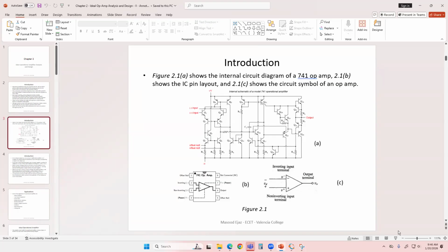The IC that you're going to use is the 741 IC. You will see a dot, basically, that represents that the pin on the left side of the dot is number 1, and it goes 1, 2, 3, 4, and on the other side 5, 6, 7, 8. Similar to the different ICs that you have used in your digital circuits. That's how the pin layout goes. On the left side, go down, and on the right side, go up.